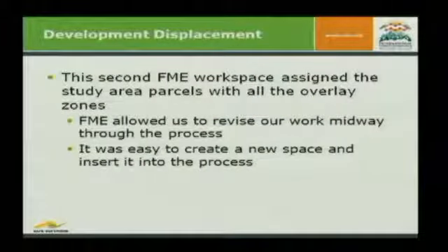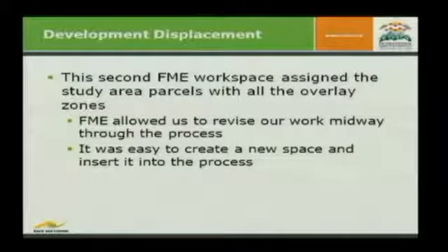So the second FME workspace assigned the study area parcels with the overlay zone. Through our process, Chris realized that we needed to add more data and attributes to our analysis to finish. The City of Carlsbad, in which McClellan-Palomar Airport is located, has a number of overlay zones that have more restrictive design standards than the base zones underneath. So, for example, if you have the Coastal Resource Protection Zone, which overlays a number of different base zones, you're going to find that your ability to build a taller building or a certain number of floors is going to be restricted due to the overlay zone, and that directly affected our ability to calculate a maximum buildable square footage for each parcel.